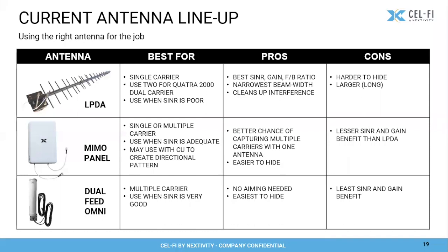What I'm getting at is, if I go to a low elevation and I'm looking across the building next door, and just a few feet above it I can kind of see the tower at some far off building, that's not good. Even though I can see it and it's line of sight, really half of my view to that antenna has been blocked. In that case, I'd want to up tilt my antenna a little bit and not have that Fresnel zone so impeded by this other structure. So it just depends on the site, right? You've got to see where your tower is, and again, you can always take measurements, right?